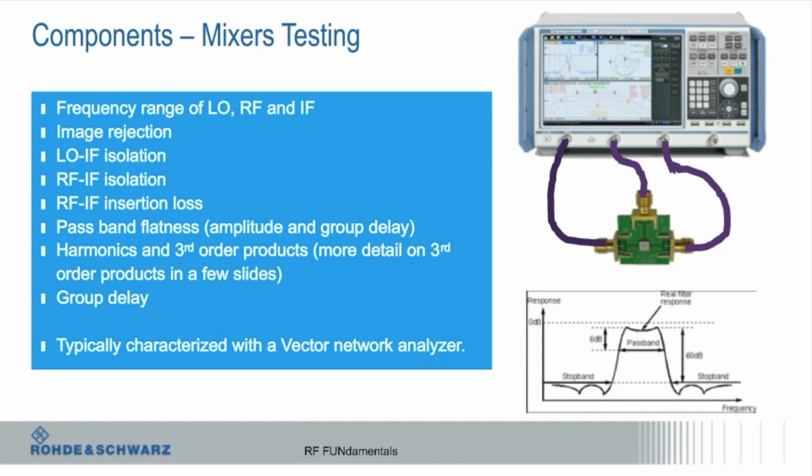Okay. So what are some of these measurements? This is showing you a bandpass response of a mixer. In reality, this is probably a mixer with a filter, but most of these things don't work from DC to daylight. They have some defined frequency range they work over. So some common measurements: I want to know what's the frequency range of all three of those signals. So when I measure the output, maybe I'll fix two of them and then vary one of them and see what happens. If I vary this one, what happens to this one? And probably it's going to go down over frequency.